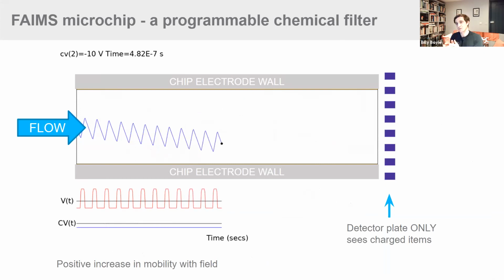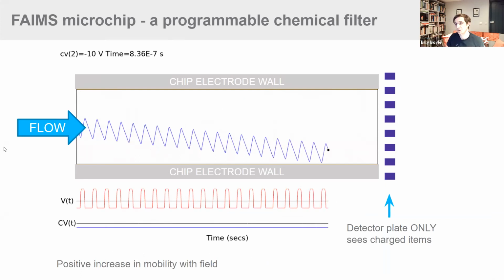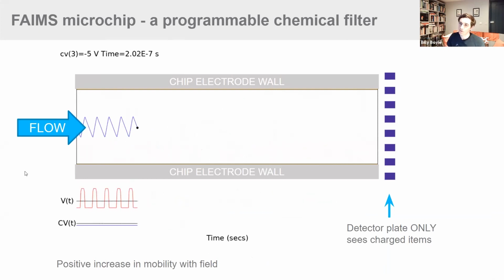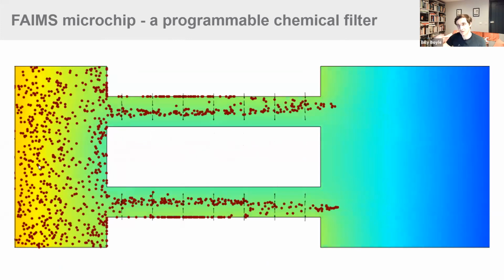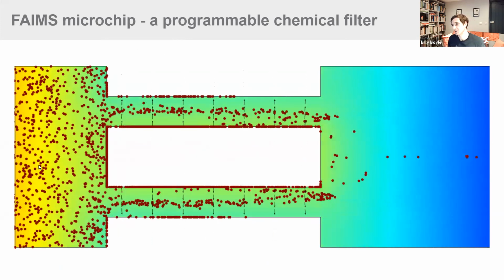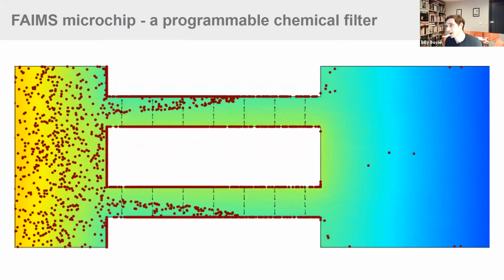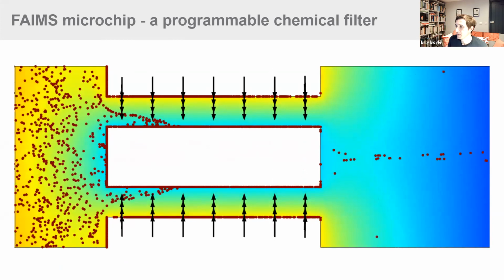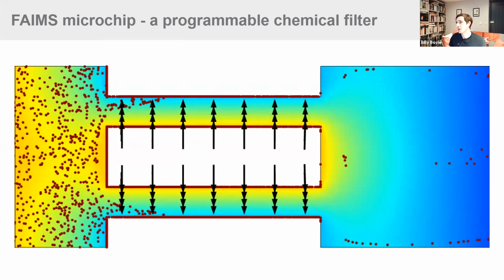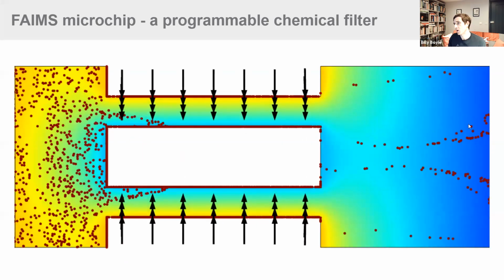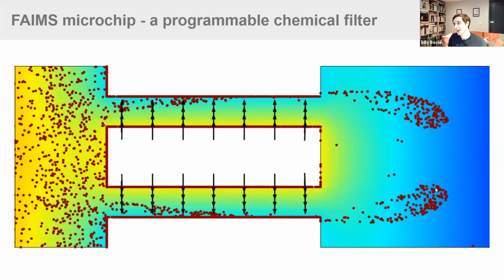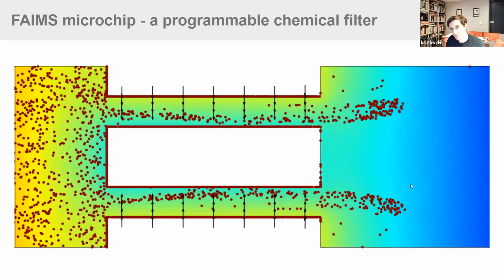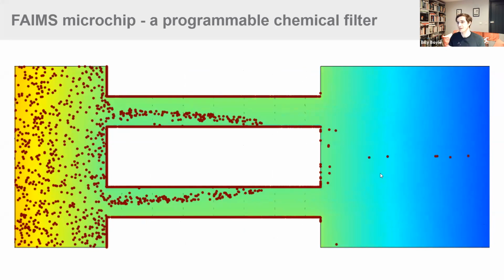So within the silicon MEMS device, we have many of these channels etched the whole way through the silicon wafer. And then when you look at a flux of ions coming through the device, this is just a simulation that shows how ions move through the device as you alternate this waveform. What you get at the back are these target compounds. And again, this could be explosives, biomarkers, and breath, you name it.